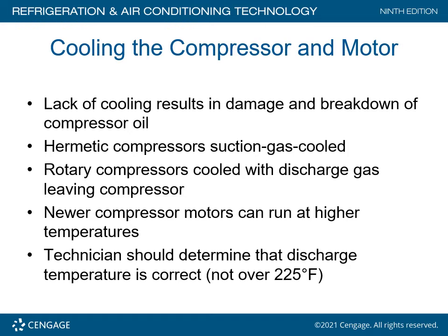Rotary compressors are cooled with discharge gas that leaves the compressor. Newer compressor motors can run at higher temperatures. Technicians should determine that the temperature is correct on the discharge line, but not over 225 degrees. It's been shown that if you have a temperature of over 225 degrees on the discharge line, you will cause the oil inside that compressor to break down.